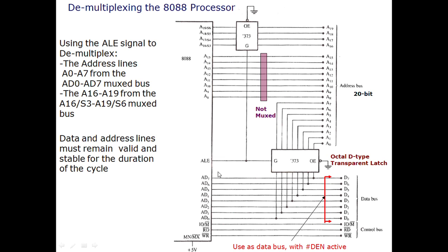So the microprocessor puts a 20-bit address on these pins AD0 till A19, and when that address is sent through these pins, the microprocessor will send a high signal on this address latch enable pin, and this will select these two chips, these latches, and these latches will allow the inputs which would be taken from these 8 lines and also from these 4 lines to be connected to the external buses.